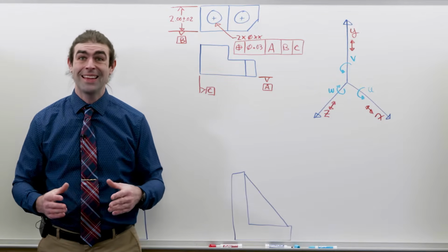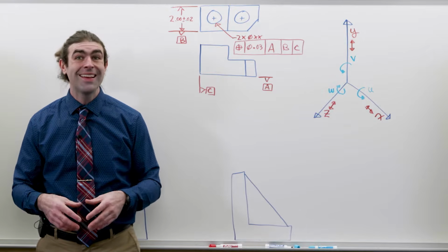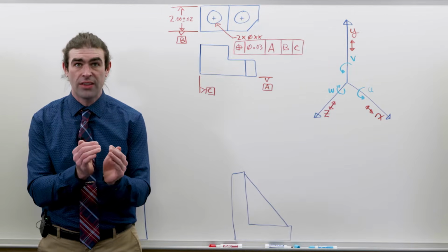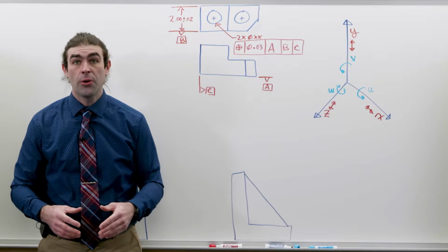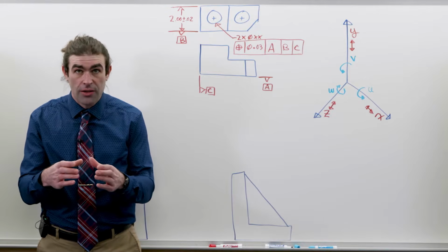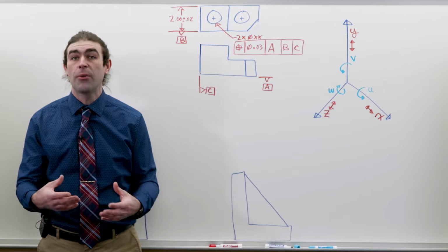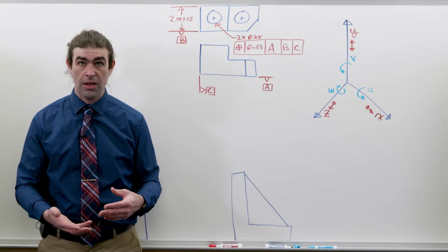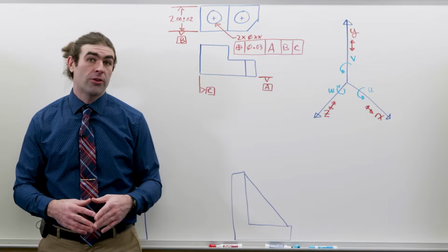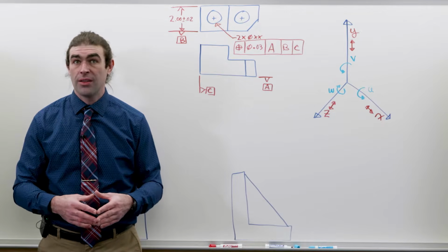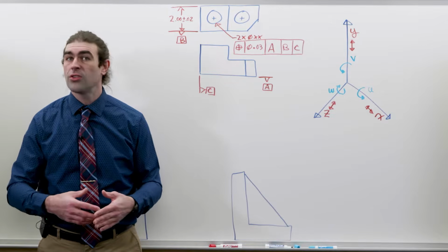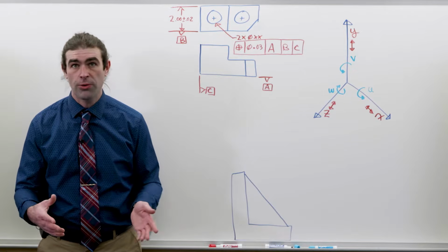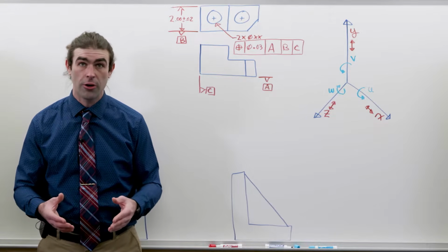If your datum is an external cylinder, the datum simulator is an internal cylinder that collapses onto that external cylinder. So imagine a collet or a chuck squeezing onto something. That would establish the axis of that cylindrical datum. True geometric counterparts are used or simulated with datum feature simulators. Okay, so just inspection equipment. Or if you're using a CMM, the computer code in the CMM will just figure it out for you.